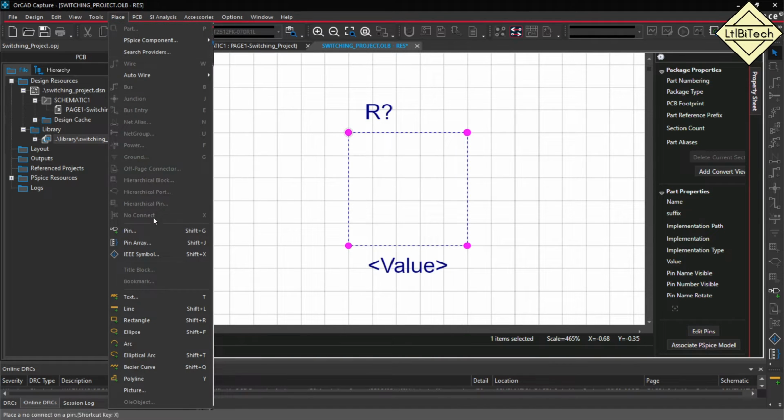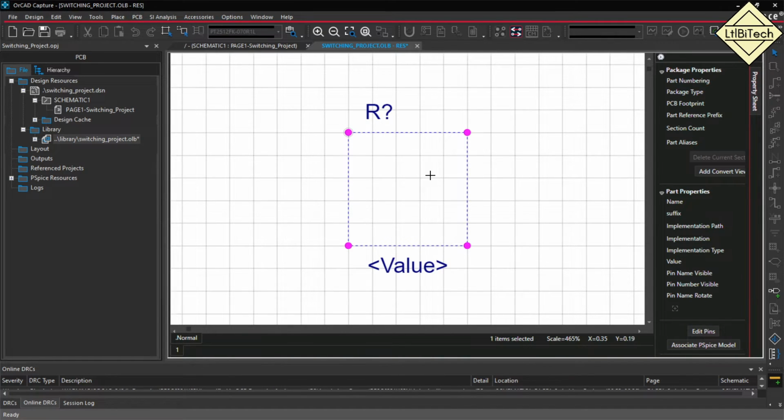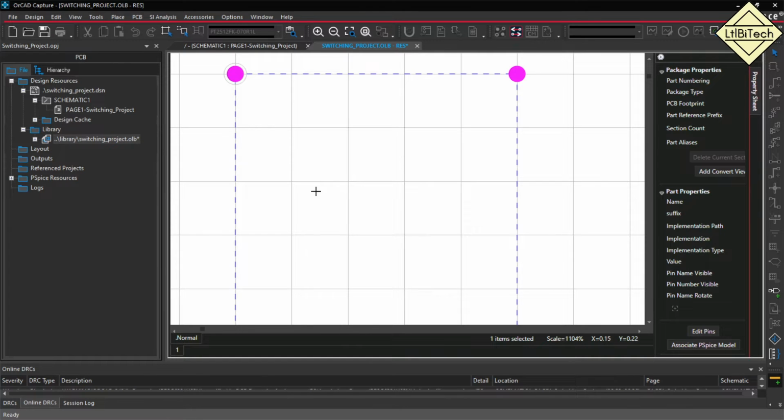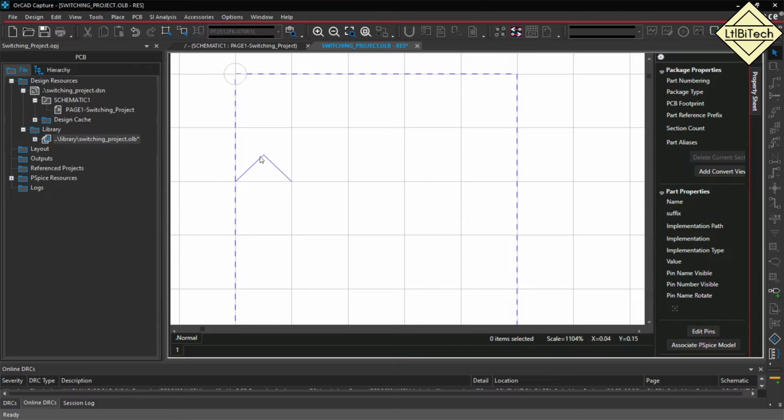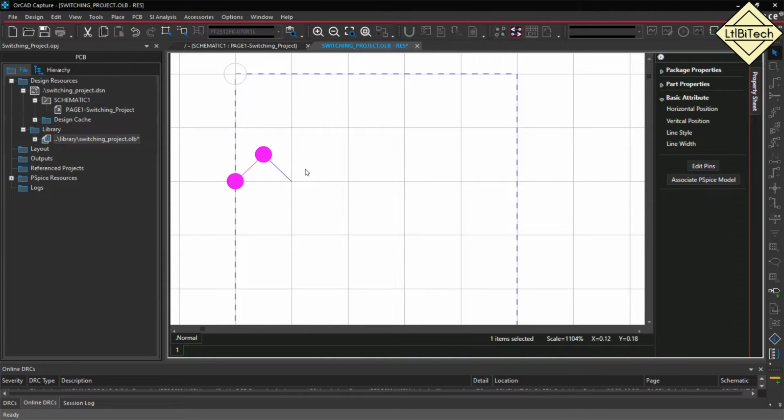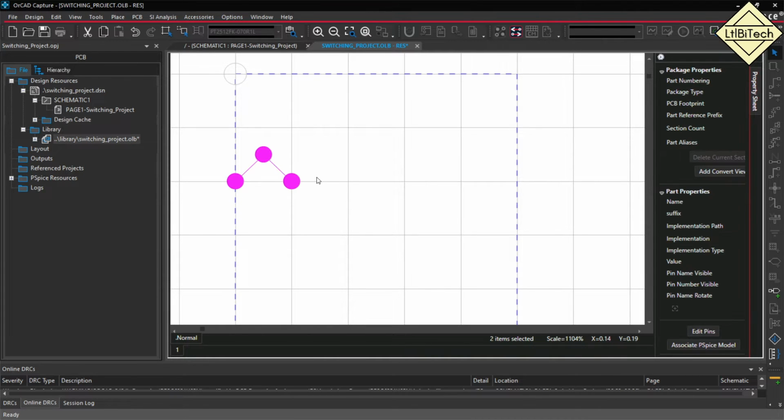We can go to place here, choose a line, and you can draw a zigzag line. Click here. I'll draw the zigzag line within that particular box. Right click and end wire. One is enough. Select with Control and then select, so both segments were selected. Now you can use Ctrl C for copy, Ctrl V for paste. Select here and again select. I just use 4 zigzag lines.